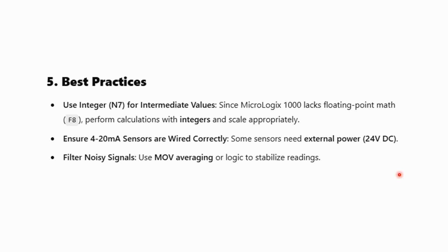You also want to ensure that your 4 to 20 milliamp sensors are wired correctly. Some sensors need external power, such as 24 volts DC. You may also need to filter out noisy signals, where you can use some moving averaging or some logic to stabilize readings.